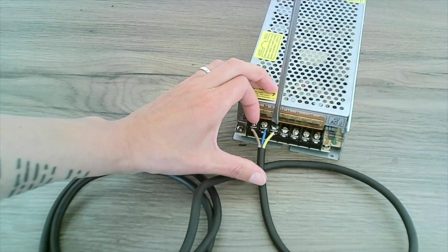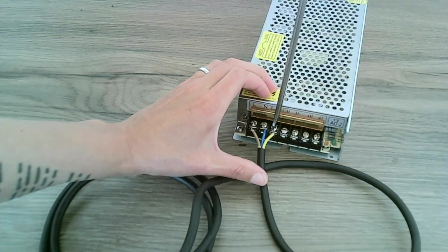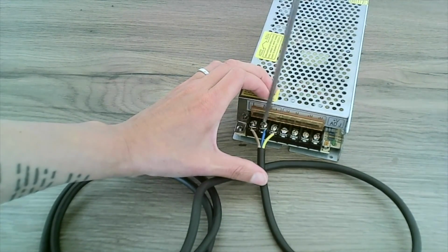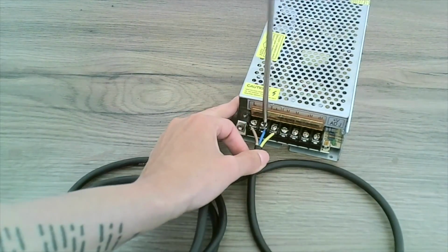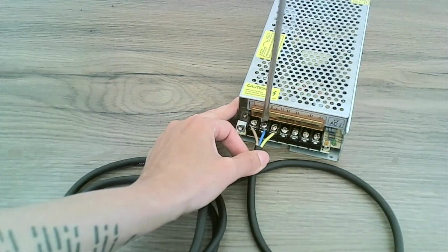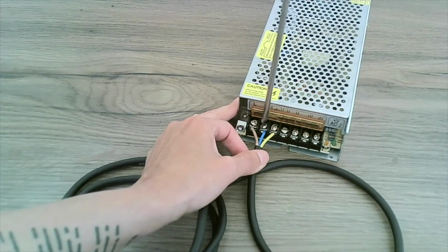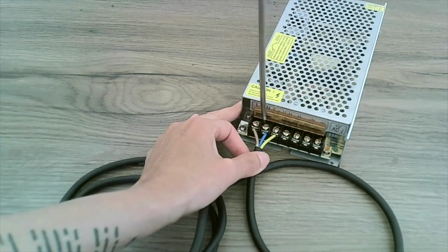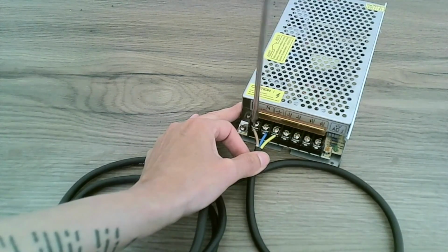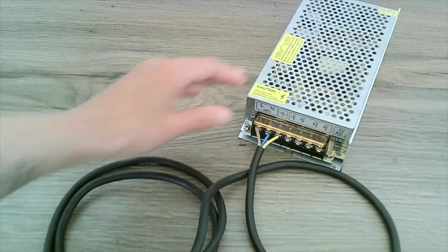Finally, triple check your wire order, as you can blow up your power supply by getting this backwards. Once you're happy with your work, I like to put a piece of electrical tape across the top of the pads so there's no chance that you could touch them or drop a tool and inadvertently short the connections. Some power supplies already come with a piece of protective plastic. AC line voltage is dangerous, so be careful.